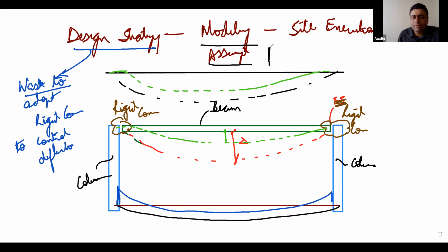So in my model, actually, I will have to do nothing, because in all the analysis software that we use, whether it is STAAD or ETABS or SAP2000, whenever we join any member to member, let's say these are line elements, by default they are joined as rigid connections. They are joined as rigid members with each other. So in the model, we will have to provide no release, and we model them as per the default setting in the software.